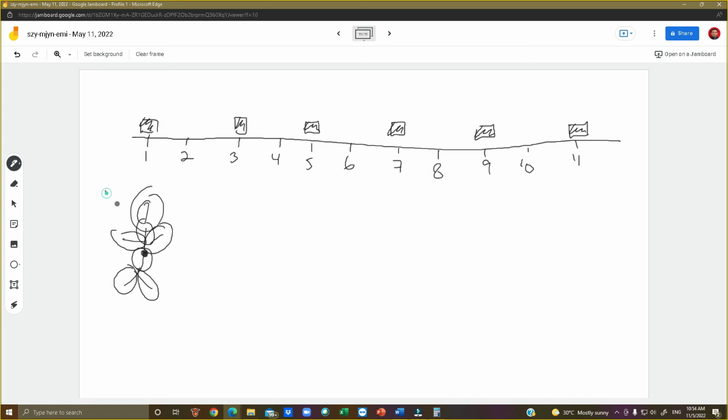In order to do human like this, kita kena ada lukisan rajah dia, the sketching of human doing a certain action, and we need to find out the center for every single segment. Kita kena cek center dia dekat mana. Because this center will serve as dia punya D. Okay, and the weight of that particular segment will serve as dia punya F. Sama lah macam yang ini. Penny ni dia punya F. Distance ni dia punya D. So the concept is similar.